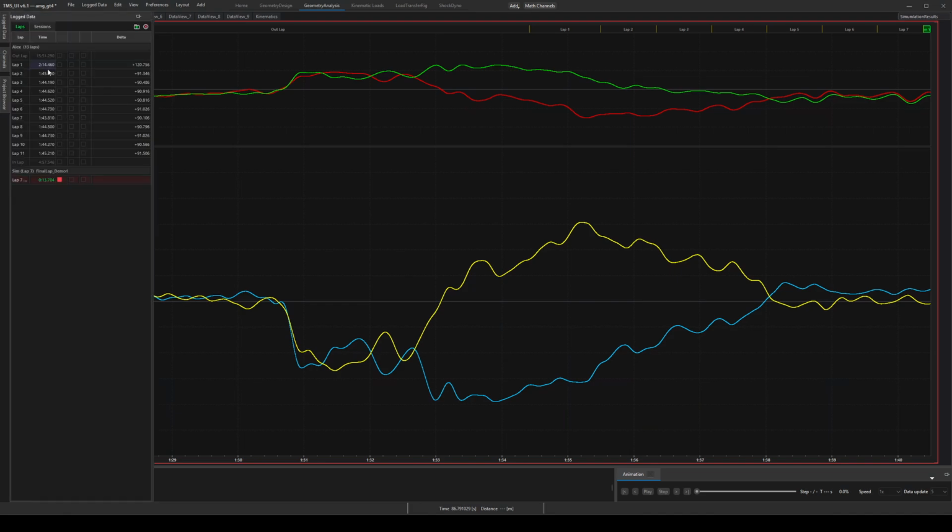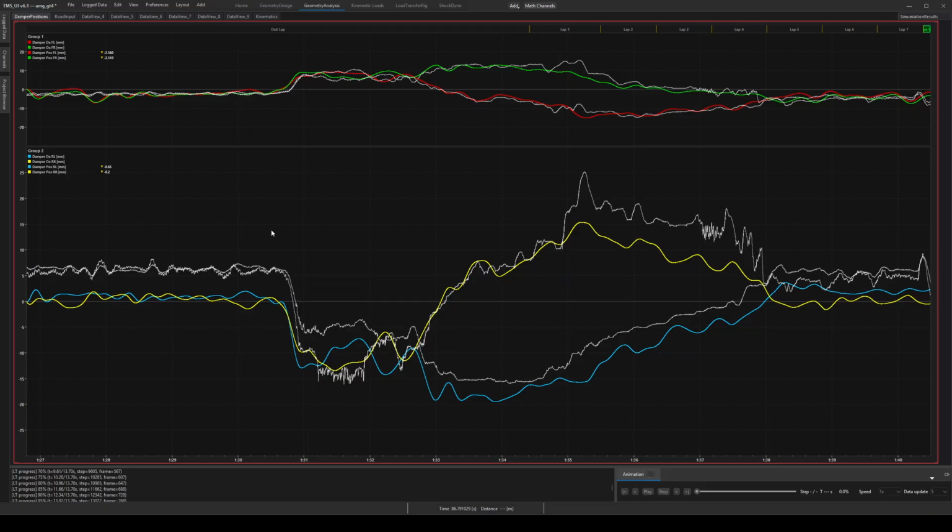The largest error is in the rear damper positions. In this case, that makes sense. The data comes from a GT4 car with a relatively small rear wing, and the front splitter does not appear to generate much aerodynamic load.